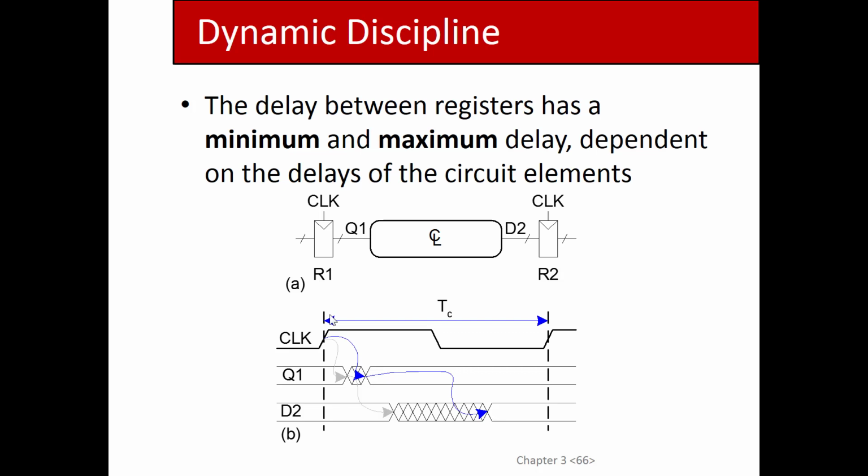It's how long the clock cycle is. The clock cycle has a falling edge in the middle, but who cares? Nothing cares about that unless we're doing something on both the falling edge and the rising edge. But generally speaking, on the chip, you don't. Memory does this; that's what DDR memory does. But internally on the chip, you generally have the clock set up such that the time from rising edge to rising edge is minimized, right? So we don't care about that falling edge. Don't let that confuse you. You ignore the falling edge. You just look rising edge to rising edge.